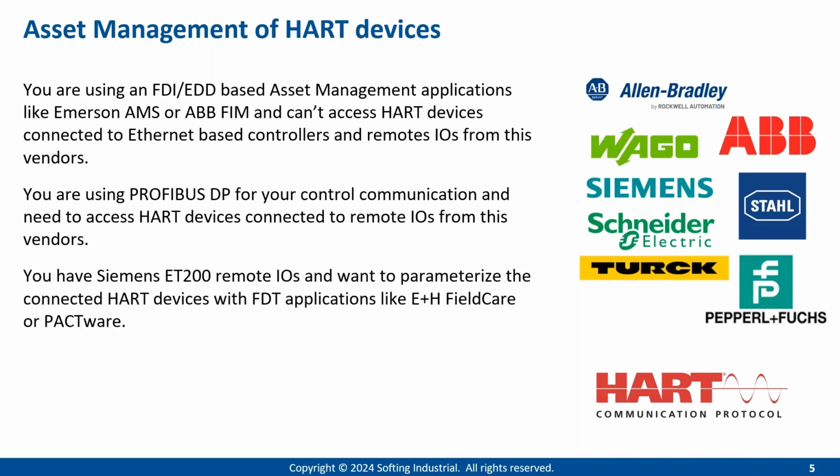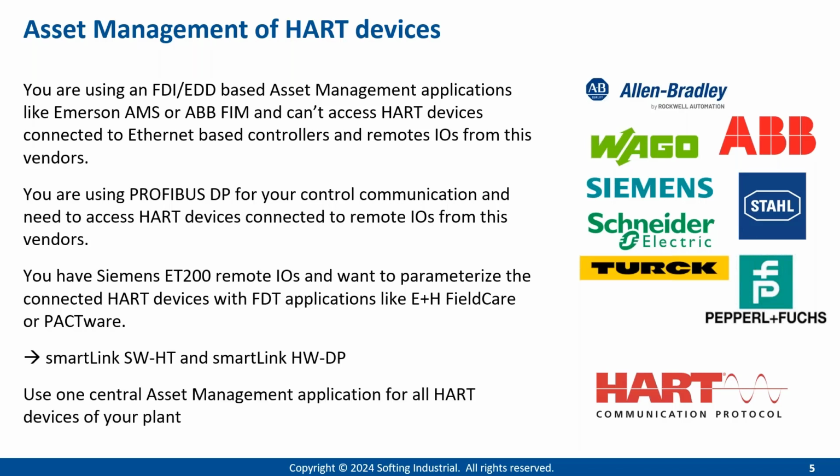Or, the third one: you have Siemens ET200 remote IOs and want to parameterize connected HART devices with FDT applications like Endress+Hauser FieldCare or PACTware or any other FDT-based application. Then the solution is our two products, smartLink SW-HT and smartLink HW-DP. I will come later to a little more detail on these products, but both allow you to use a central asset management application for all the HART devices in your plant.